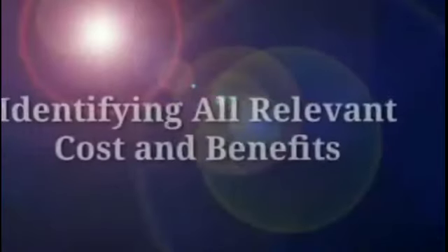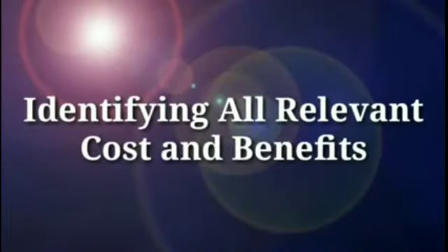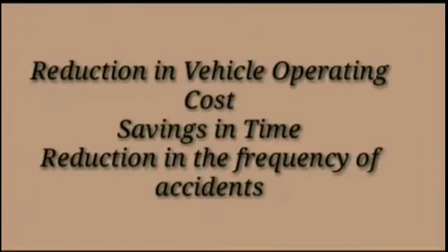The application of cost-benefit for project assessment in the highway area is made more complicated by the wide array of benefits, and many of those benefits of improvements of transport projects equate to decreases in costs. The primary grouping that contains this type of economic gain is termed user benefits, and this grouping includes reduction in vehicle operating costs, savings in time, and reduction in the frequency of accidents.